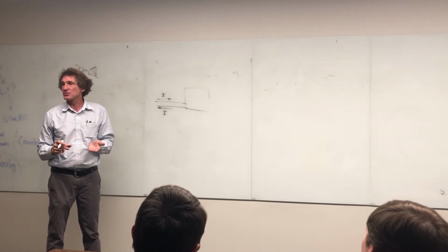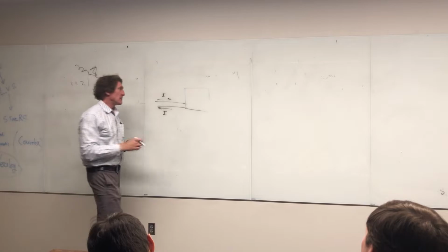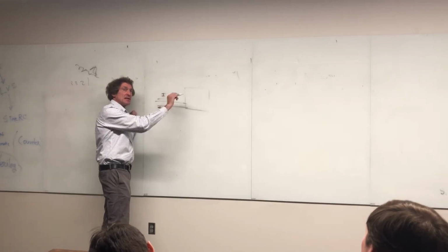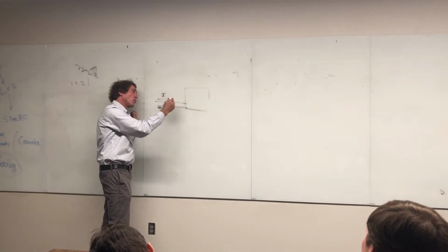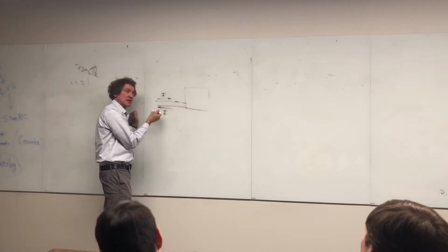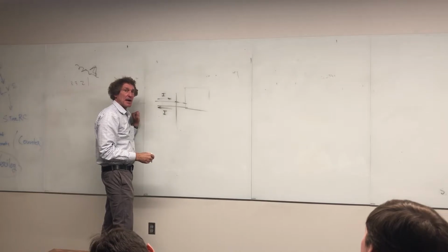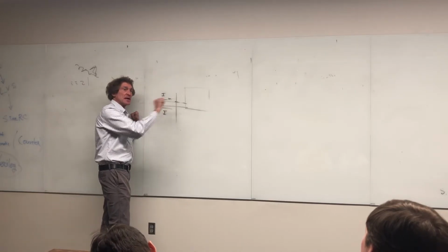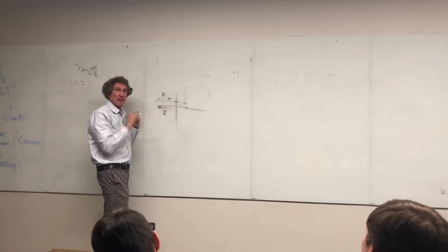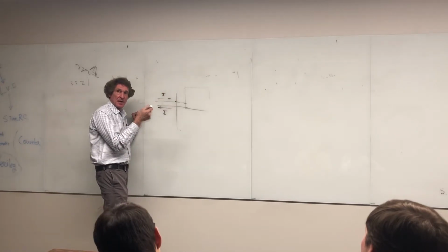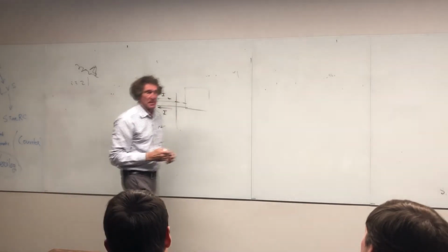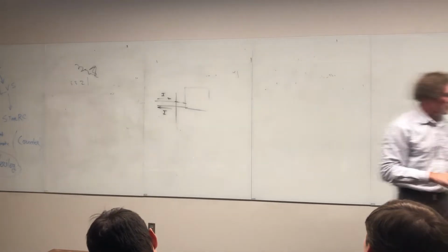That's called a differential mode signal. It means what you're basically doing is sending current down one through the positive lead, and it's returning in the negative, right? The net sum of the current crossing any straight line path is 0. Do you follow me? So if I look at the net current flowing that way, it is 0, because the same amount going one way is coming the other. Got it? And that's what you want.